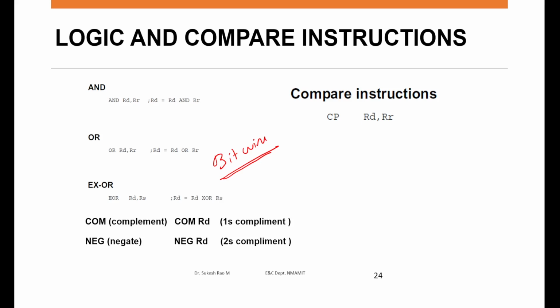So some special instructions: the compare instruction is something that is important. So obviously compare instruction is supposed to be checked with the carry flag. That's an obvious thing. So carry flag, C flag, is to be checked. What happens when RD is greater than RR?